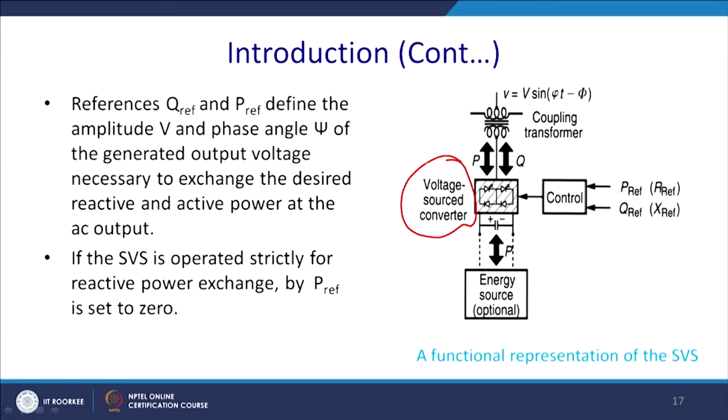So, this is a voltage source converter. According to the switching, it will generate the reactive power, and if it just comes with the capacitor to meet the losses and the harmonics, then it can inject the voltage and compensate the reactive power. Otherwise, if you have a storage device, it can also inject real power.